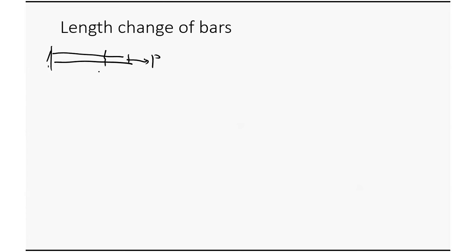Now, if I make a cut here, what's the stress here? How do you find the stress here? You find the internal force here. So what's the internal force? You draw this free body, this half, and this is the N here, and this is the load P here. So what do you have? Equation of equilibrium. What's the N? N equals P.